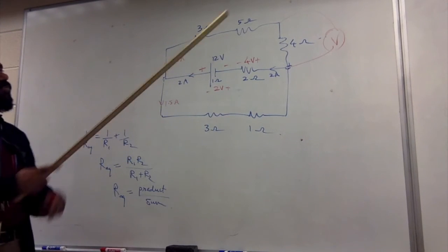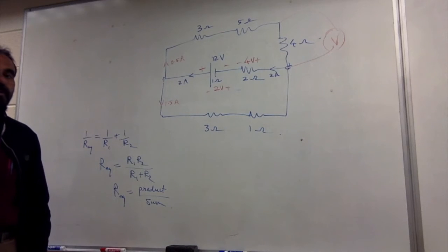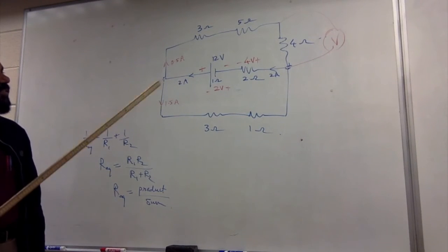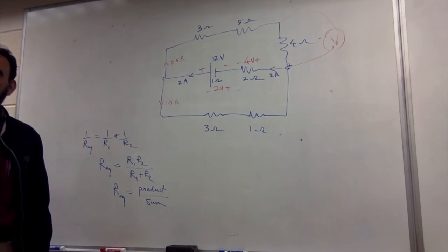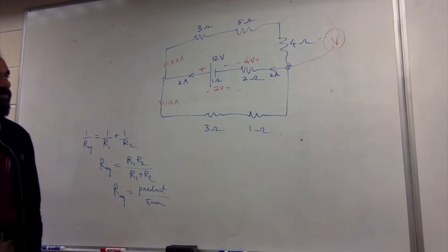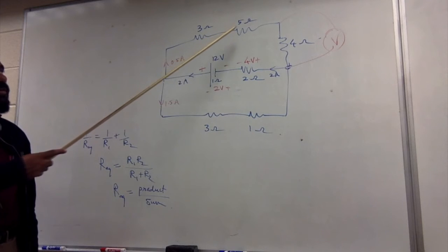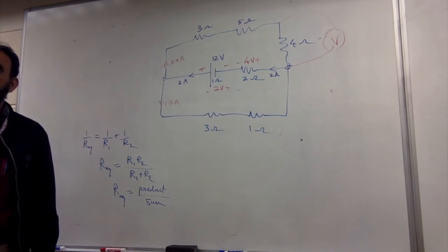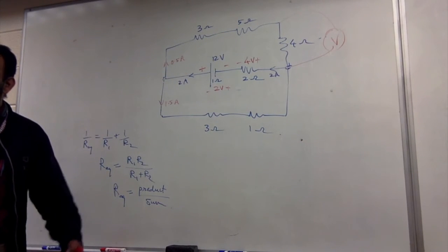So if in case you find that the potential difference here is not 2, it's something else, that means there is some problem with the circuitry. There's some problem, there's a defect. And the defect could be, you thought it was 5 ohms, but it's actually 50 ohms. You know, those kind of defects.